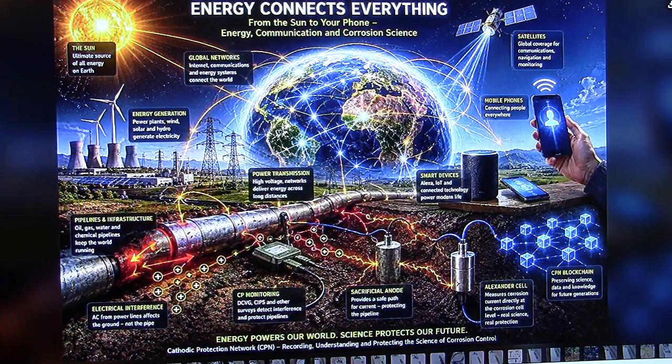And, as Luis correctly points out, fault currents and leakage currents can involve the soil, grounding systems and other conductive paths as the electrical circuit seeks to return to its source. So we have to distinguish between the electrical disturbance in the ground and the electrical reaction occurring at the pipeline. These are not necessarily the same thing.